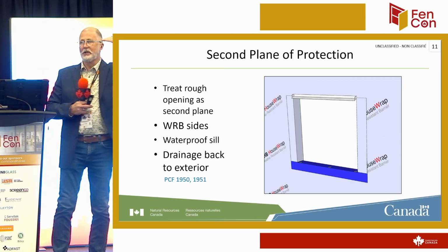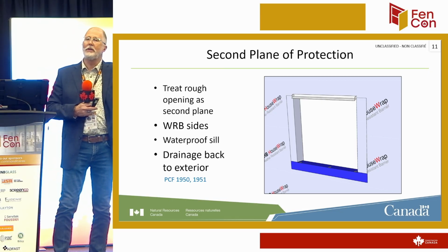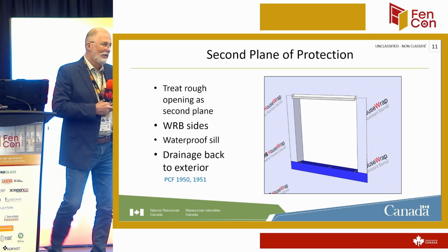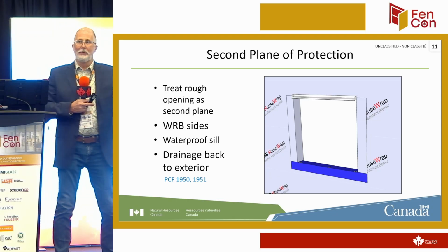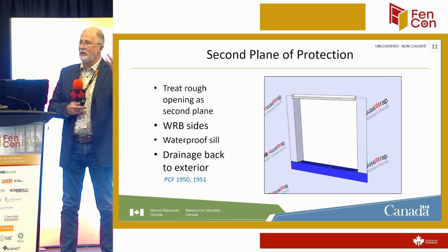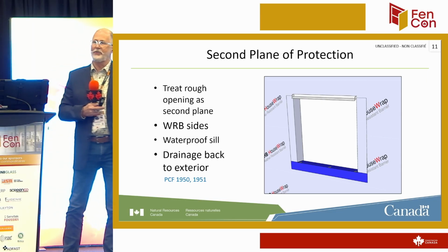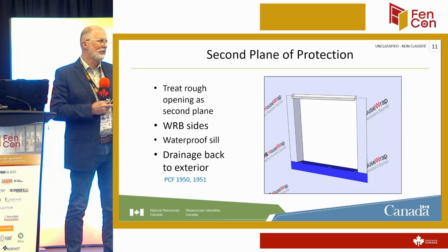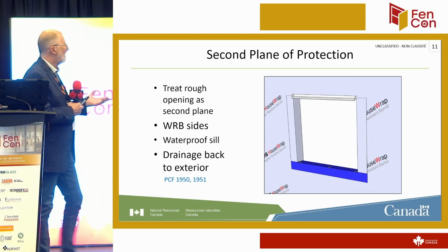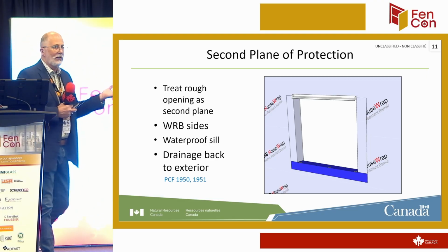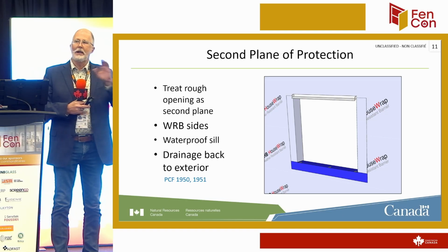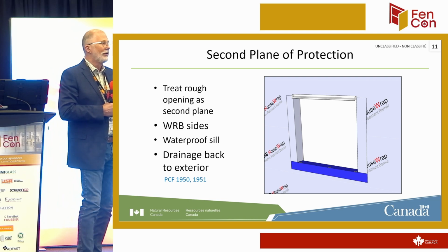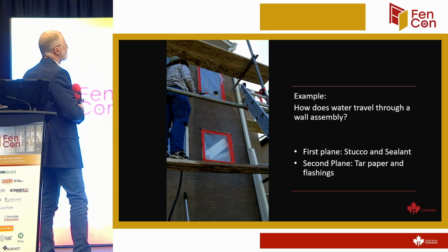Like, this is a factor of everything. We have higher insulation levels, we have higher air tightness levels, and what are the two things we need to dry a building out? We need air and we need heat, right? That's what absorbs the moisture and holds it in suspense into the air instead of depositing it. So we build these modern houses and we put all this extra insulation in it, and we use the same construction method. That doesn't make sense. So we need to get rid of that moisture, but old buildings, you take them apart and they look like they're in pretty good shape. I'll bet you if you added extra insulation to them and sealed them up the way we do a modern building, they wouldn't survive very long. So it's all about drying and getting rid of the moisture.